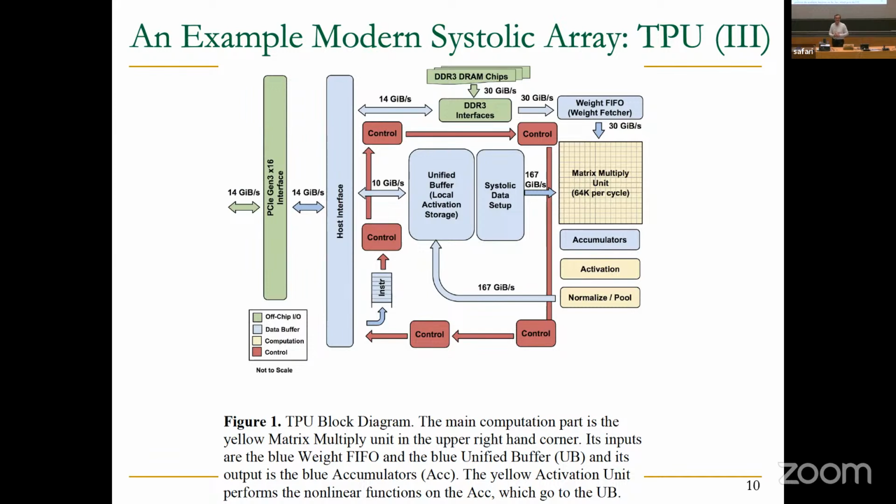Not necessarily, yeah, not necessarily. So they're probably taking advantage of the reordering internally. As long as you get the right result, it doesn't matter which order you follow. But yeah, if you think about that, in a von Neumann architecture, you have a sequential order dictated by the program, right? You have to obey that order because that's the architecture you have. Here, a lot of things can be happening concurrently. So that's one of the other benefits of systolic architectures. You're not tied to an order.